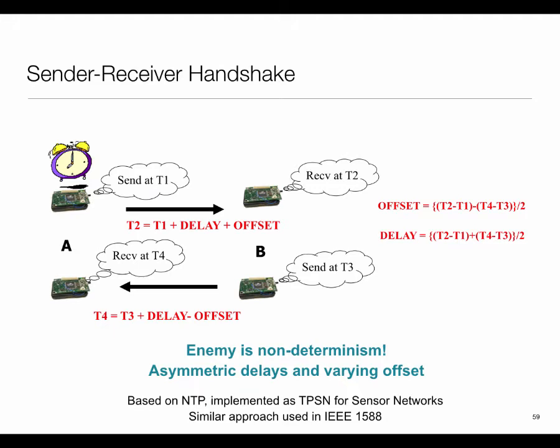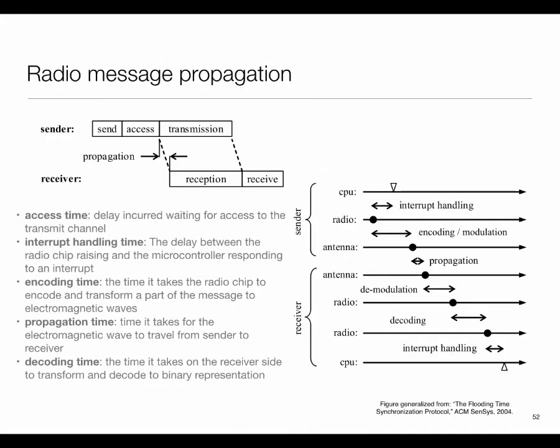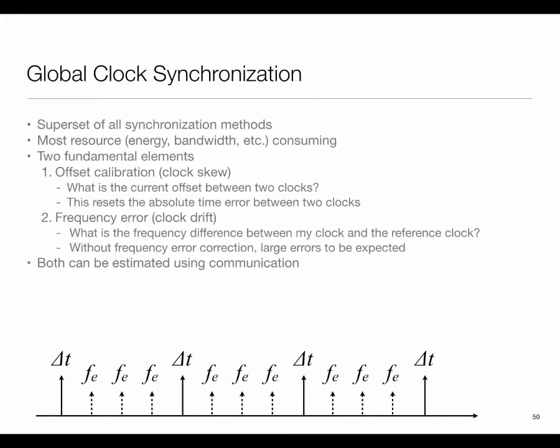So going back then, what that means is that in our arsenal we have a few things. I can pre-calibrate delays. Second, I can do a one-way transaction to measure clock drift, and also if I have pre-calibrated delay and the delay is not changing, then that also gives me offset information. And I can do a two-way handshake to get delay more directly. So typically what happens is that we employ all of these in some combination in a given system.